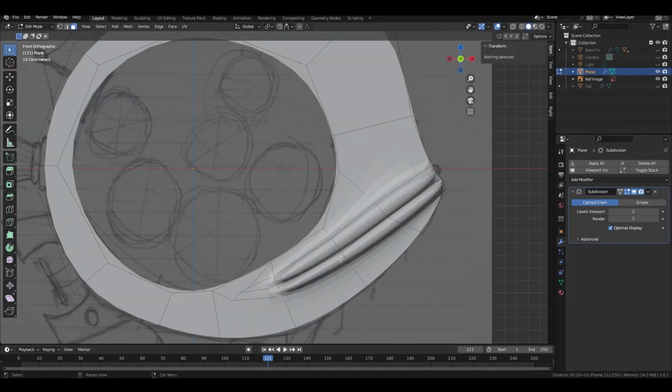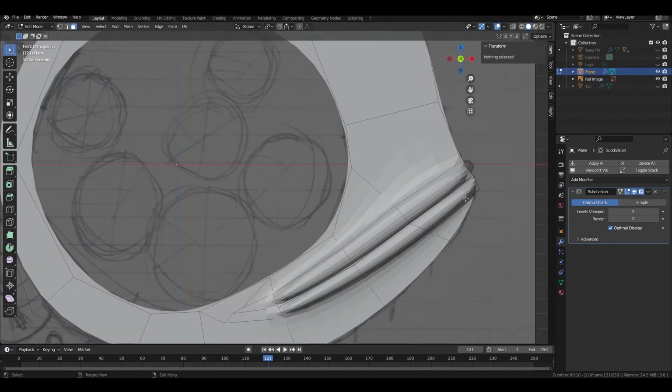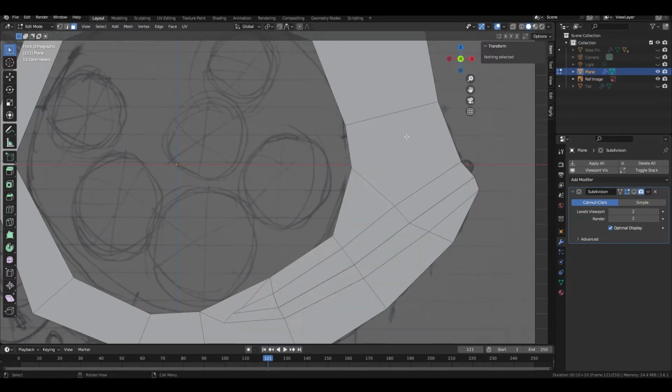Now, in the process of trying to get these extrusions to work, I've committed a cardinal sin, and that's to create n-gons. So we've got here a 5-sided shape, and down here where I rushed to join what I thought were 4 vertices, I've actually joined 5. So we really shouldn't be doing that. We should always try to have quads or triangles.